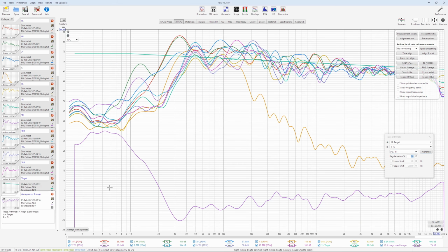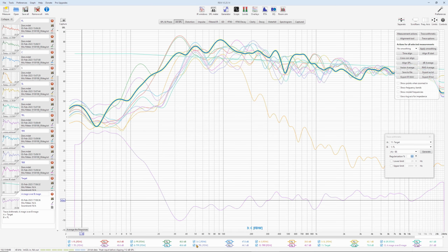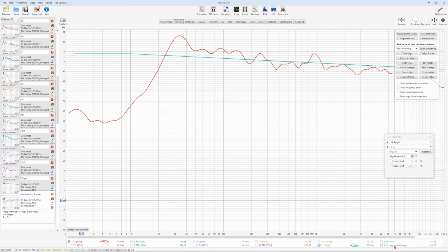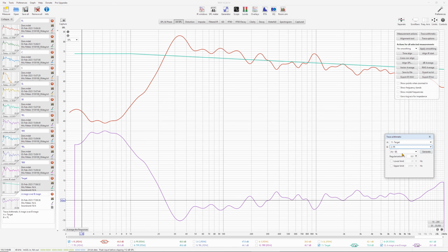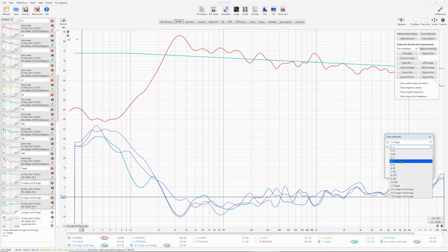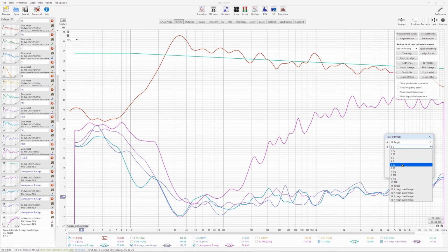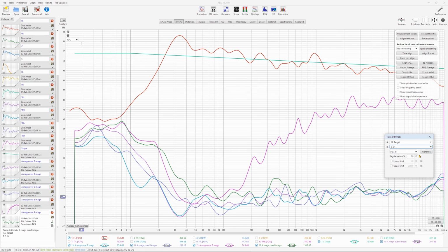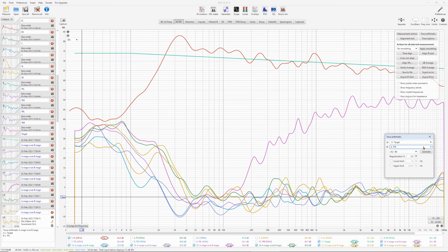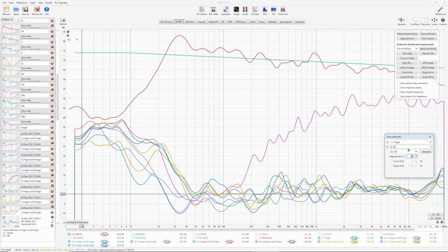And if you look at 0 dB level, you now have the inverted response for the front left speaker, which is here. This is target. We inverted it over the target curve. Okay, you have to do that for every speaker. Target over FR, target over C, subwoofer, surround left, surround right, top front left, top front right, top rear left, top rear right.